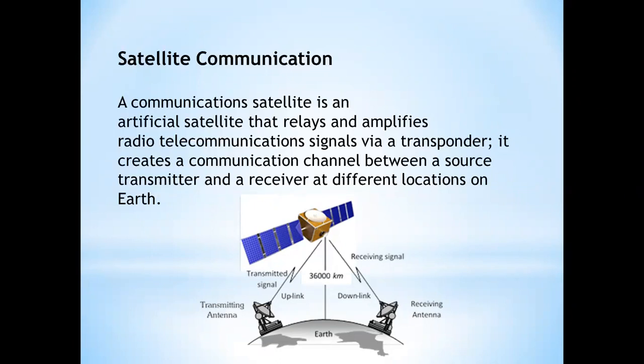The signal which is transmitted back to the receiving Earth station is called the downlink, and it is normally at a frequency of 4 GHz. Thus, the satellite has to receive, process, and transmit the signal. All these functions are performed by the unit called the satellite transponder. A communication satellite generally has two sets of transponders, each set having 12 transponders, making a total of 24 transponders. Each transponder has a bandwidth of 36 MHz, which is sufficient to handle at least one TV channel.